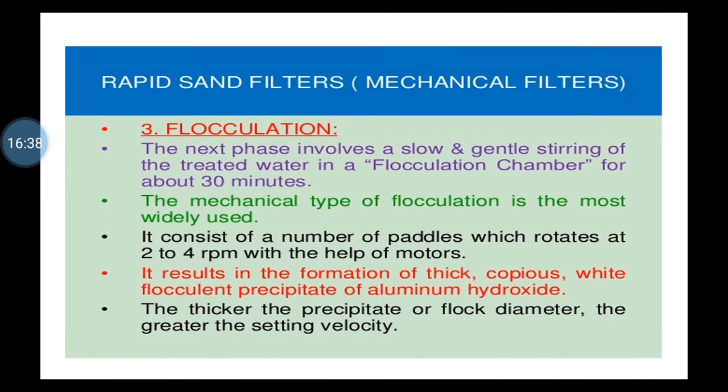Then the third step is flocculation. From the mixing chamber, the water is subjected to the flocculation chamber, where the water is gently stirred at a slow speed. The speed is very slow, and it is done for near about half an hour. Mechanical type of flocculation is done.